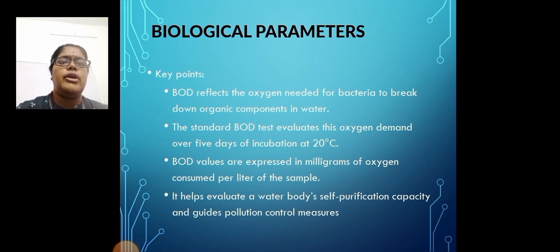So the key points you have to remember here: BOD reflects the oxygen needed for the bacteria to break down the organic components in water, and the standard BOD test evaluates this oxygen demand over 5 days of incubation at 20 degrees centigrade. BOD values are expressed in milligrams of oxygen consumed per liter of the sample, and it helps evaluate a water body's self purification capacity and guides the pollution control measures.